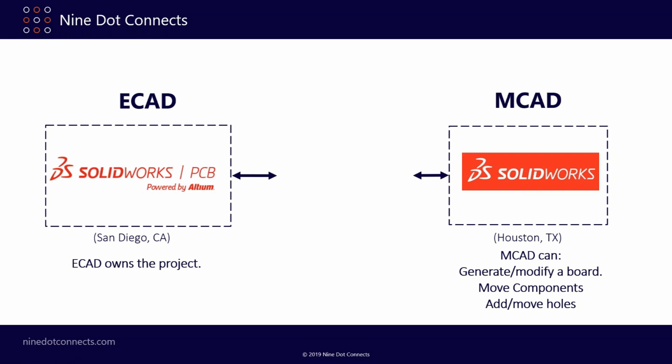Because they're completely different architectures. For example, in SOLIDWORKS PCB, almost everything that we do is going to be grid-based, and we are very heavily reliant on these things called primitives. We have a primitive for a via, a primitive for copper, a primitive for a polygon pour. Even our components, which are considered primitives themselves, are made of different primitives. So they're very specifically defined. We cannot create new primitives, and we can't even change the properties, meaning add a new property or remove a property from any of those primitives. So we've got to work within that primitive set.